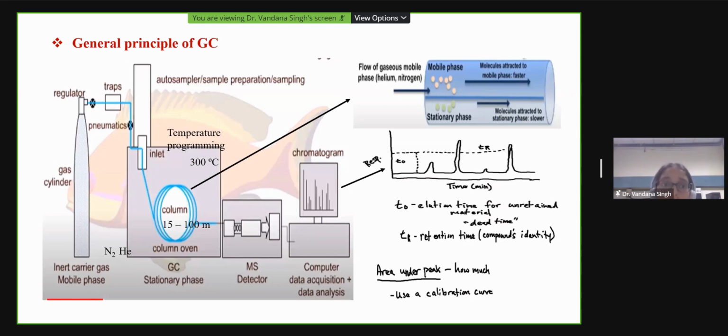If the analyte concentration is high, we should dilute our analyte so that there is no overcrowding or overloading of the sample. Certain kinds of samples can also be directly injected through a microsyringe using a port in this column.